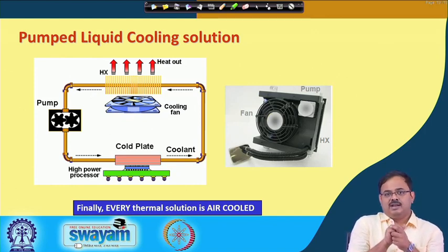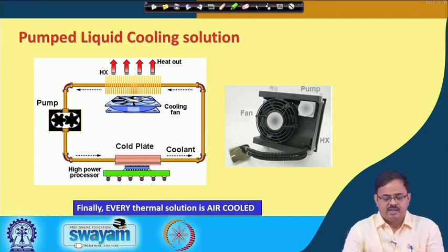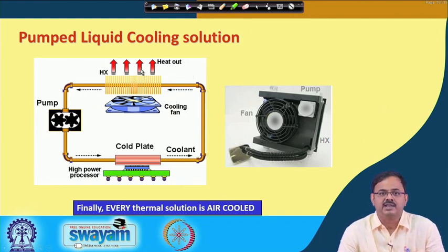And of course, there are other advantages of liquid cooling as well. Of course, there are disadvantages as well: pump reliability, and it is a more complex system. But the advantage is this part, the heat exchanger part, can be away from these circuits and components. So, all the problems about vibrations because of the fan running at a few thousand RPM, because of dust, etc., will not be there. Okay.